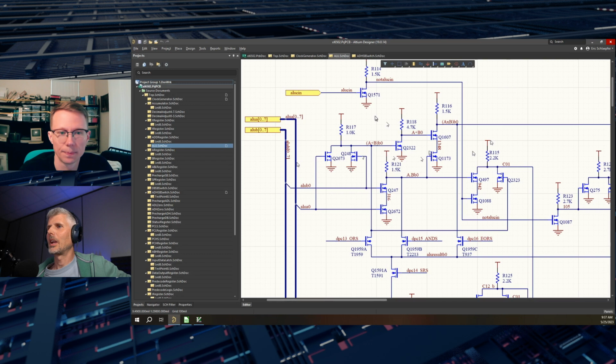Yeah. So just looking at this now, all the transistors are N-type. So was this all done with NMOS logic? Yes, this is entirely NMOS. So all those pull-up resistors, that's where you're burning a lot of the power then? That's why I'm burning more power.